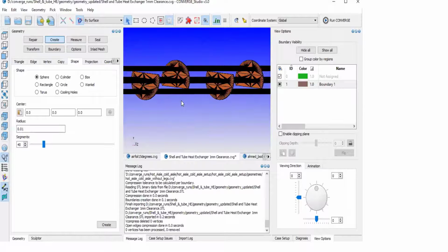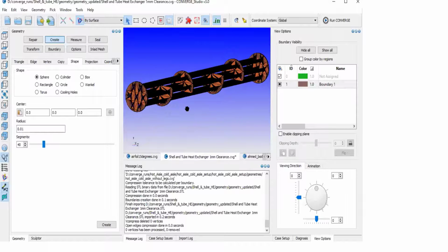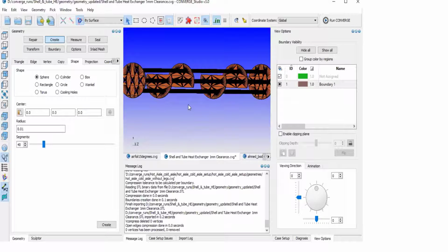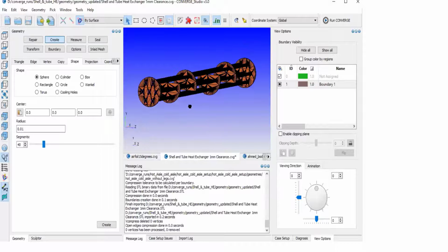It looks simple, right? But when it comes to cleaning up the geometry, removing the unnecessary parts which are not necessary for this simulation, or which don't have any involvement in the results you are looking at, that is what you have to learn. And if you learn this methodology, irrespective of what domain it is, you are good to go. A few things will obviously change a little bit, the way it is programmed at the back end. But if I tell you that to set up the case there is a CFL number, there are input conditions, those things will not change. Mesh, those things will not change. Correct. So that is what.